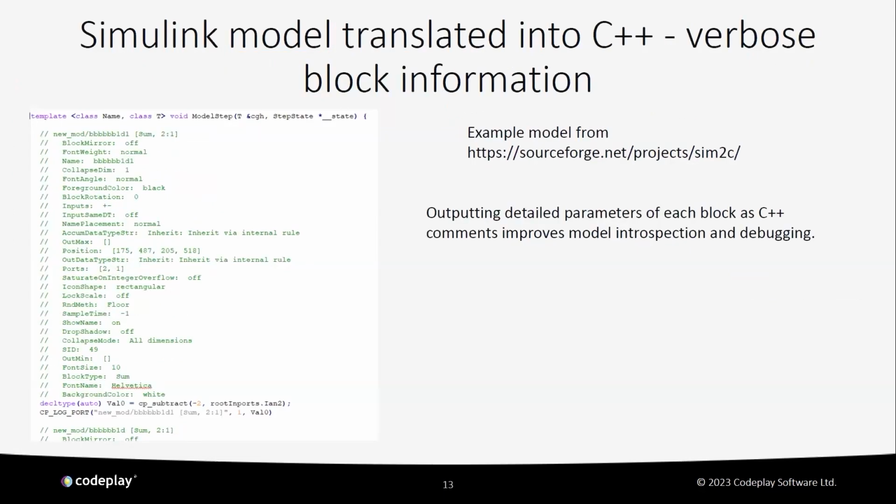One other advantage is you can have a look at the block parameters. This allows some kind of introspection that isn't really possible with Matlab, because if you want to introspect all the parameters, you would have to go through all the blocks and click through all the different options, and that might be quite time-consuming and tedious. So it's much better to output all the block parameters as comments in source code, and that allows you to search through certain things and verify and look for certain parameters that you want to evaluate or tweak.